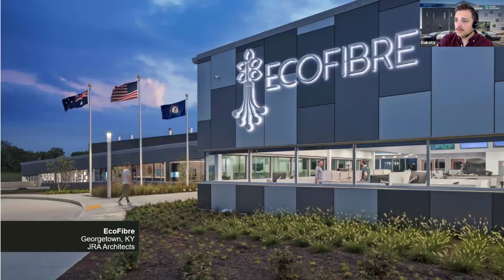Let's talk about some of the considerations with different metal facade types. We talked about ACM, we talked about plate. Each metal facade system comes with its own considerations, and we definitely need to keep those in mind. We already talked about the benefits of ACM, plate, and single skin, but these have some challenges, right? With ACM, there's going to be some fire code challenges depending on the project and the location. Plate systems are going to have some geometry limitations due to their rigidity and their material, which is what we want, but can also lead to some limitations.